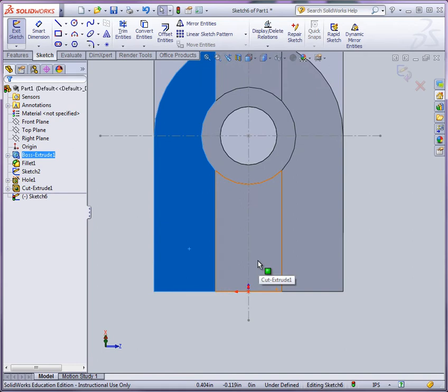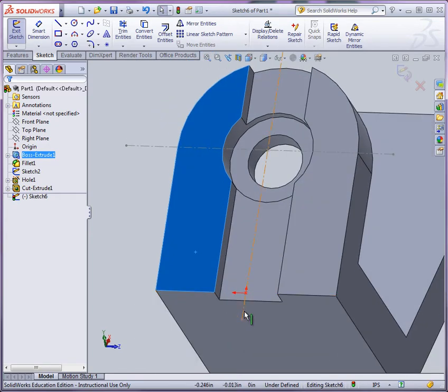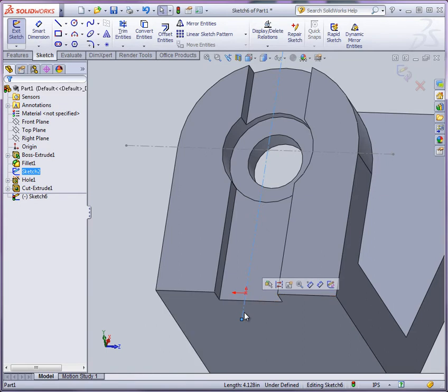So in this view, I can more easily lay out the sketch, right? Now, here's another thing. Notice how I already have sketch geometry here, right? I want to borrow this sketch geometry. I want to be able to use this sketch geometry in my own sketch, right? Well, one thing I could do is I could actually use convert entities.